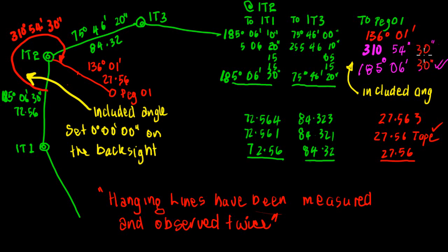Similarly, if we add these together, that will give us 0, 0 there, 01 there to 60. We've got a 6 there, and then we've got 180 is 490 minus 360 gives us 136°01'. So that's the little check that I do. I give it the old two ticks just to show that I've checked it.